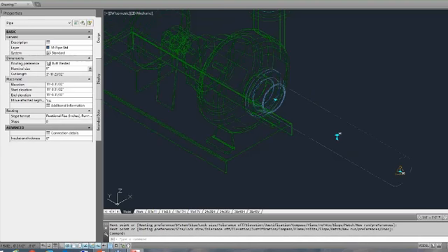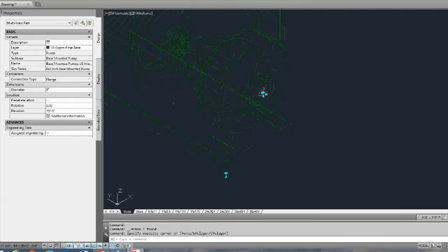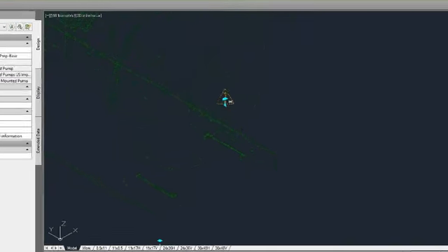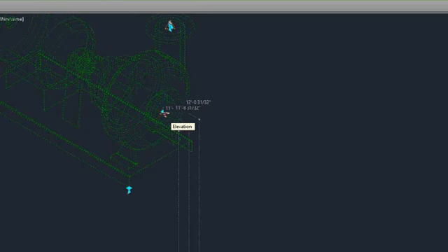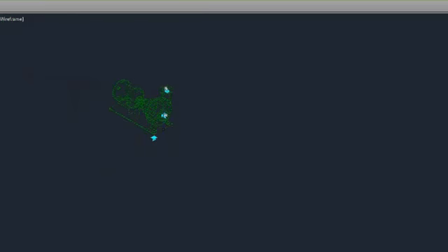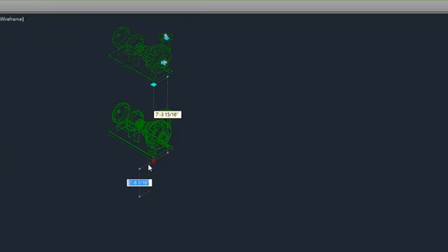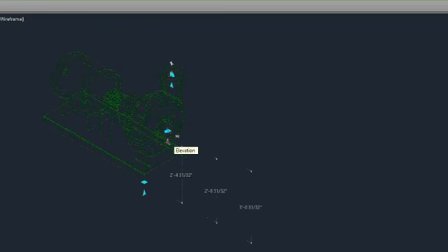If I delete those and get back to just the regular grip and go down to, again, the elevation grip of the connector, you'll see that this time there are, and it's hard to see, 3 lines going down the length down to 0, 0, 0. If I move this pump down to, say, an absolute elevation of 1 foot, it's a little easier to see those three lines. What those 3 lines correlate to is the bottom of pipe, center of pipe, and top of pipe.